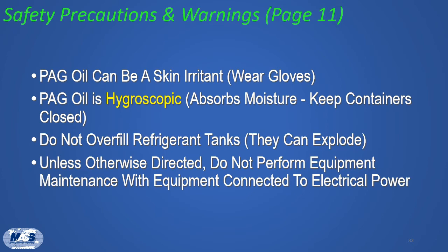Also, be sure not to leave refrigerant tanks out in the sun or in direct sunlight. Remember that as temperature increases, so does pressure. And if the temperature of a refrigerant tank rises, so does the pressure of the refrigerant inside the tank. If the temperature or pressure of the tank is allowed to get too high, it could cause a dangerous condition.